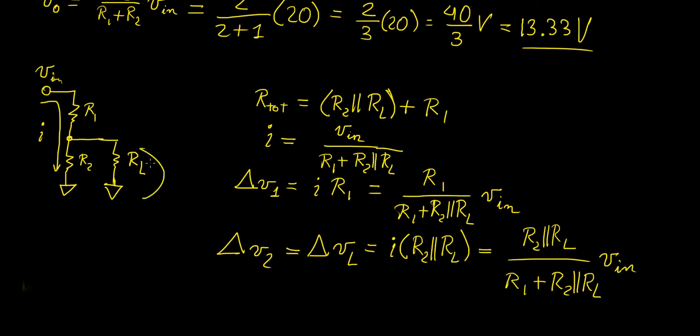So it turns out that the potential drop across the load is going to be given by this. It's going to be quite different to what you would normally get if you just had an open circuit over here and extracted the potential at this single point joining the two resistors. This is a really important thing, because when you're dealing with real circuits, you're always going to need a load, and that load is going to affect how much voltage or current you can get out of that. Of course, you could use the same thing to calculate the individual currents through each of these resistors, but that's just applying the basic concepts we already know.